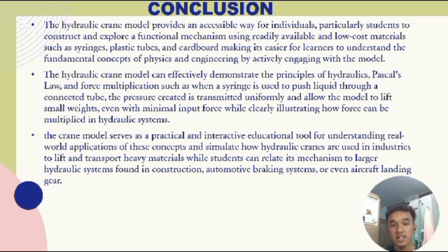The hydraulic crane model can effectively demonstrate the principle of hydraulics, Pascal's law, and force multiplication, such as when a syringe is used to push liquid through a connected tube, the pressure created is transmitted uniformly and allows the model to lift small weights, even with minimal input force, while clearly illustrating how force can be multiplied in a hydraulic system.